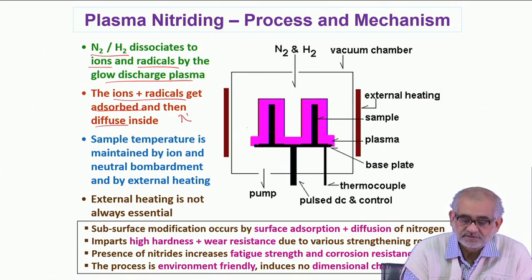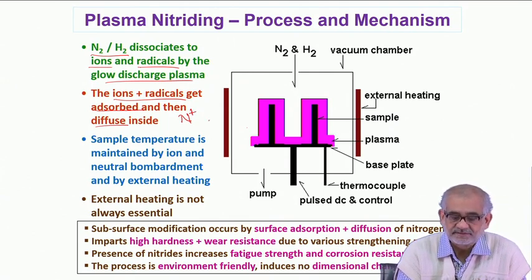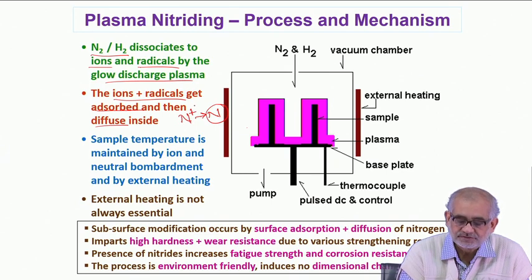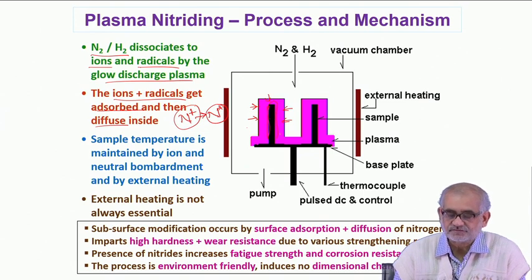In this particular case, we are talking about nitrogen, but the nitrogen in an activated state or the nascent state, actually when they come in contact with the surface, the free electron cloud from the surface allows them to convert into nascent nitrogen atoms. So these nitrogen ions coming from the environment, from the plasma, come in contact with the surface of the workpiece, acquire electrons and then reach a neutral state, but this is in an activated state, and now it's ready to diffuse inside. So nitrogen now comes from all sides, and then that's how it actually gets absorbed and then diffuses inside.